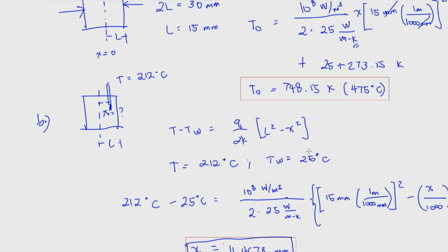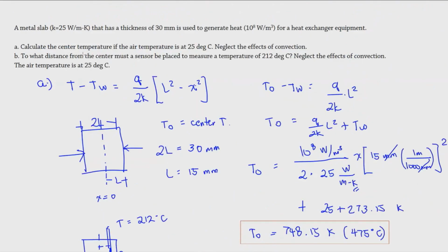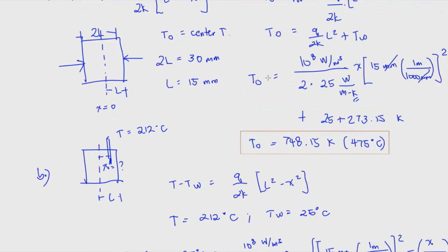And I wanted to specify something here. We've already been given the thermal conductivity, and we are assuming that it is constant along the temperature. Now, if K is given using a differential equation, we have to go back to our original equation and start deriving again and formulate a new formula for this. It will be kind of difficult for such cases.